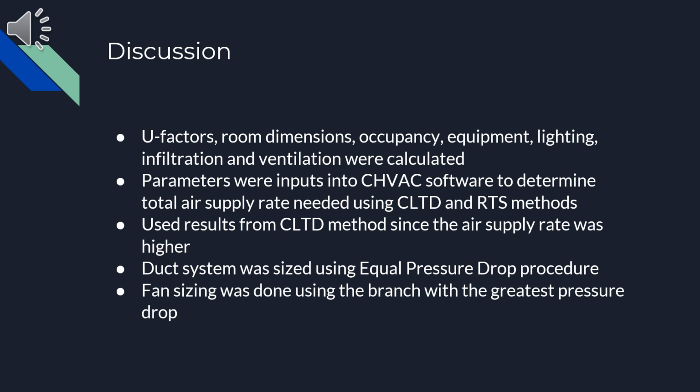The duct system was sized using equal pressure drop procedure. Fan sizing was done using the branch with the greatest pressure drop.